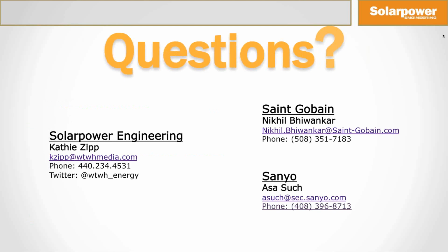Yeah, that's a good question. Thanks for asking. Yeah, absolutely. The way we have designed this is people should be able to use the same manufacturing equipment, the same lines, and similar temperatures to what are currently used with conventional PV front glass modules. So we don't expect that to change. Typically 145 to 150 degrees Celsius, and 11 to 14 minutes of lamination time. So very, very close to conventional modules.